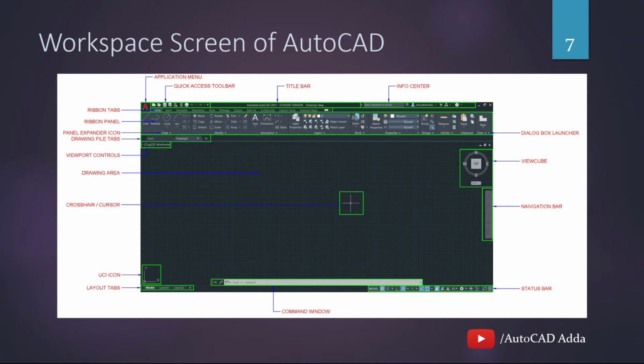Next, let us have a look at Ribbon Panel. This area holds various tools and commands grouped together and arranged systematically as per the functions they perform, like drawing, modifying, properties, dimensioning, etc. There is also a panel expander button or arrow near the panel title to display all the tools available under the panel. For example, draw panel.